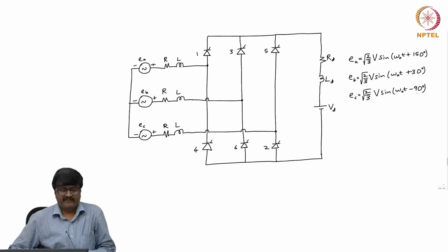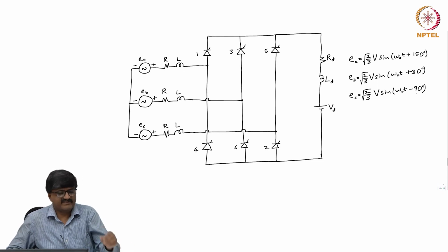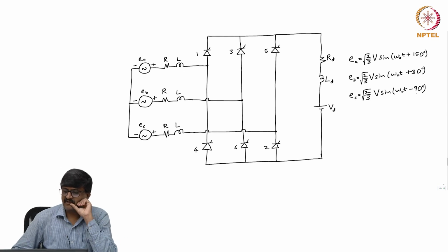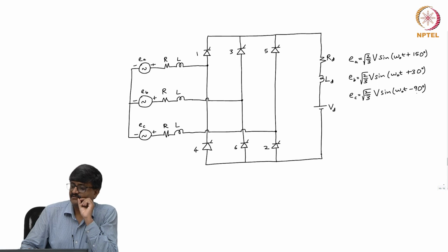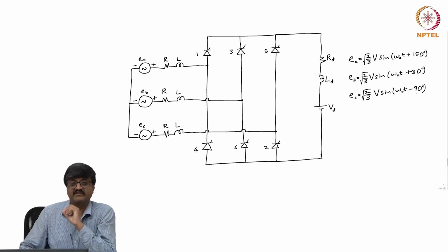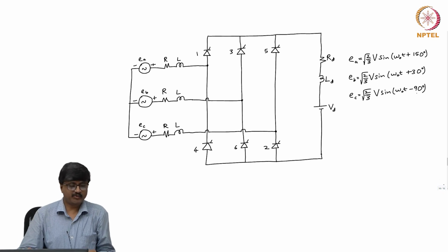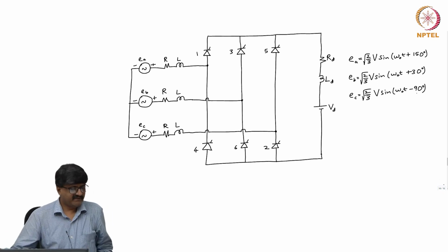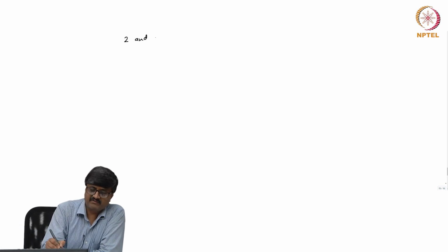So, if I want to analyze this circuit, I can employ the general steady state analysis. So, let us try to do the steady state analysis, essentially finding x1, x2, A1, U1, A2, U2, f, g. Let us start with the 2 and 3 valve conduction mode.